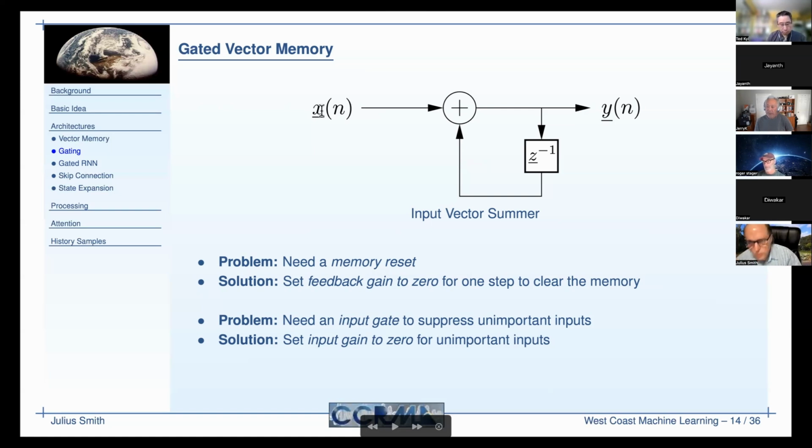But in other words, I want my vectors on the hypersphere, and that'll be a recurrent theme through everything I'm saying, because it's very clean. You can think of it as normalized signal processing everywhere. And this is a big thing in signal processing, so I'm biased by that. I'm biased by all my experience in normalized ladder filters, normalized state space filters. We could talk about that. Balanced realizations is the buzzword in the state space world. Normalized ladders are really nice. It's power normalization. It's really important numerically. So for example, a normalized ladder filter is just a filter structure.